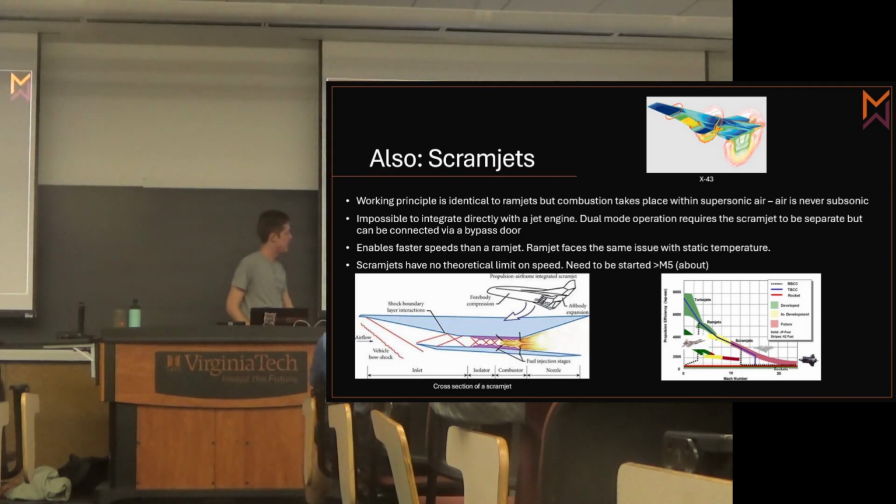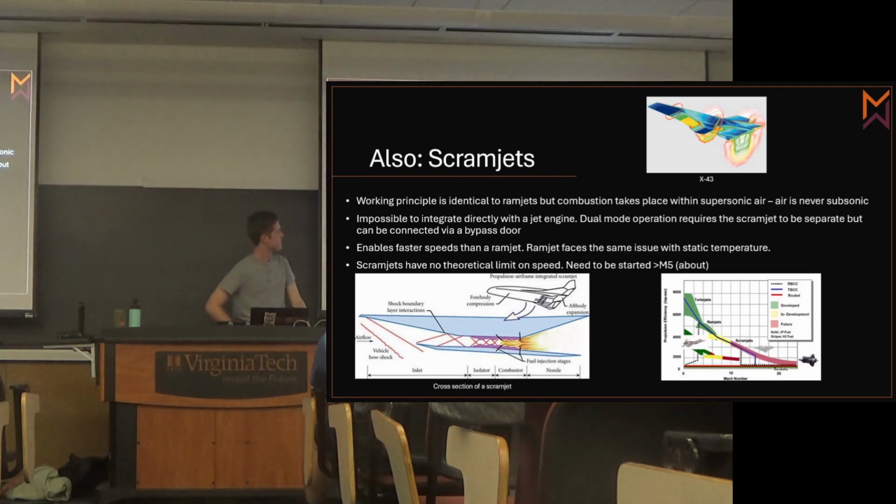So we're going to put these little bypass ducts right between the compressor stage, and we're going to take it right back out and feed it right in the afterburner. And the really cool thing about this is that it could actually operate at higher efficiencies at its cruise speed of Mach 3 than it could at subsonic speeds, which is kind of crazy. That they made an aircraft that was better at flying fast.